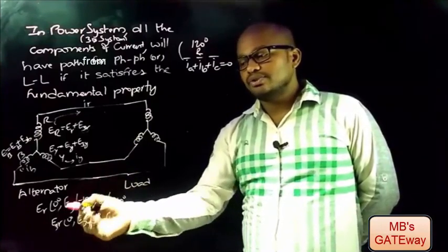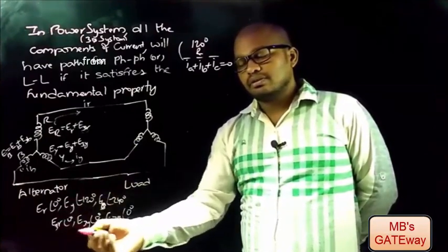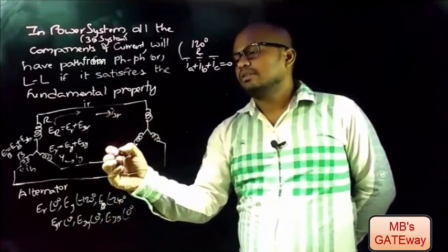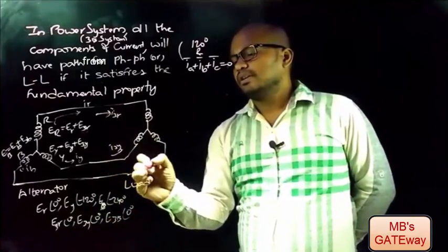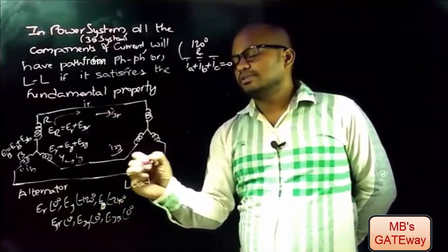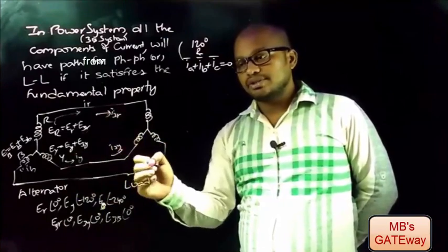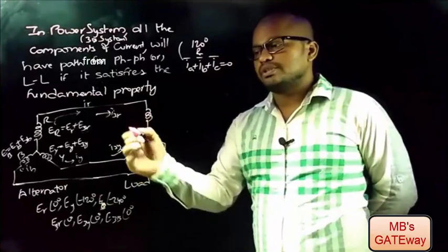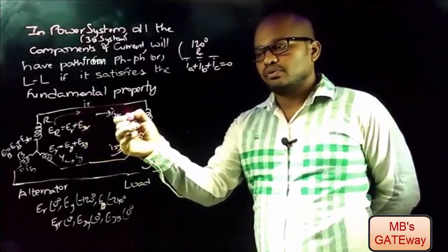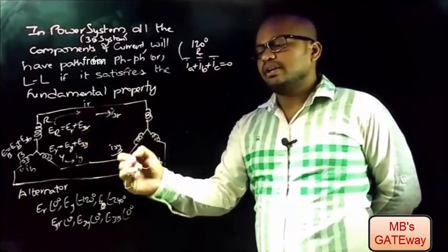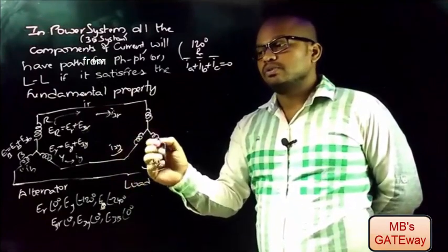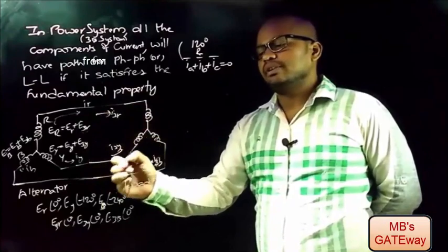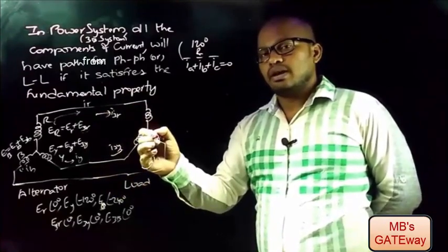All these currents due to the harmonic components, I3R, I3Y and I3B, start at the same instant, and they reach the point at the same instant. What you must note here is that for the current I3R to flow, there is opposition from I3Y and there is opposition from I3B. So there is no path for I3R. Similarly, there will be no path for I3Y and there will be no path for I3B.